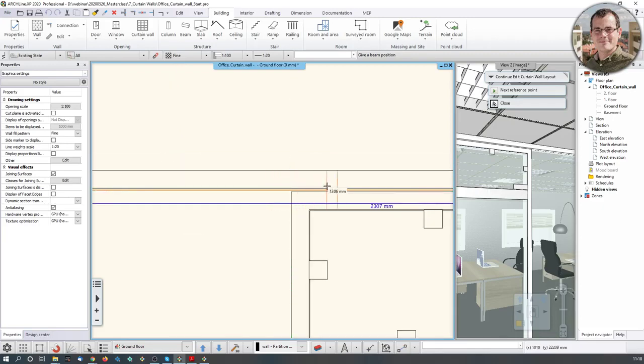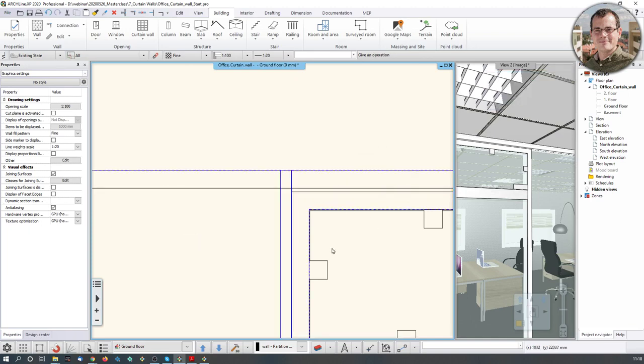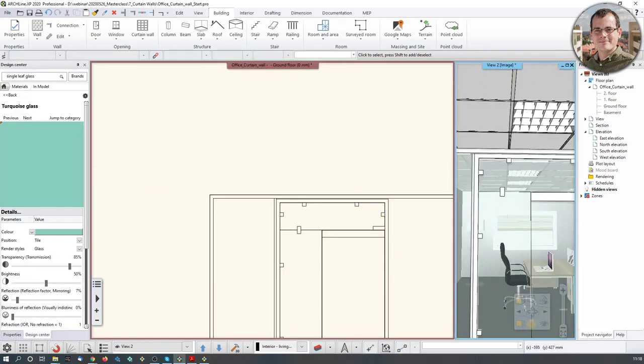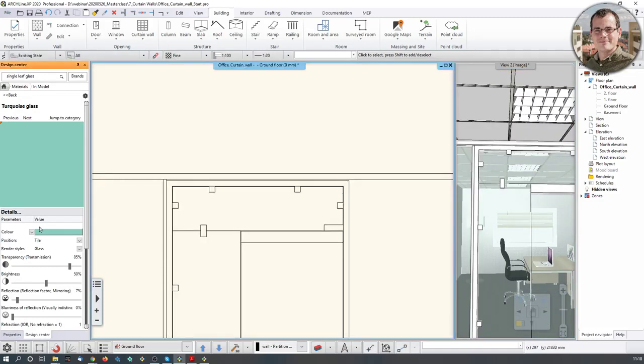By the way, when you are positioning something, you see that the cursor is on the left hand side and the mullion to be moved on the right hand side. But if you want to flip it, because this is your reference point, but you want the mullion to move here, you just hit the F5 key or just toggle it over here, and then if you click, the division would be at the right place, like that. So now I have moved the improper division to somewhere else.